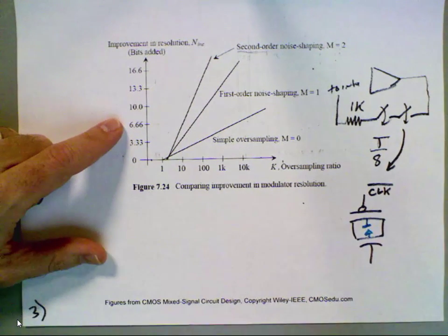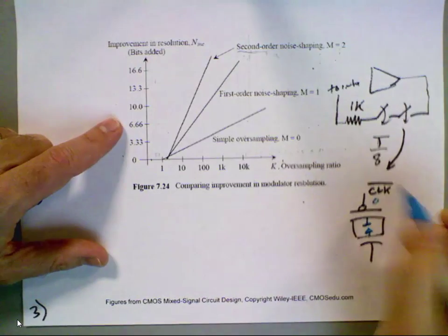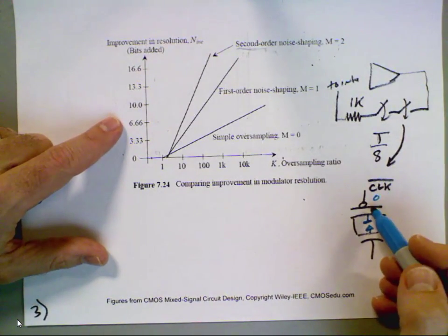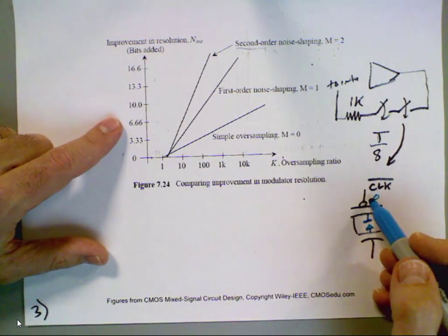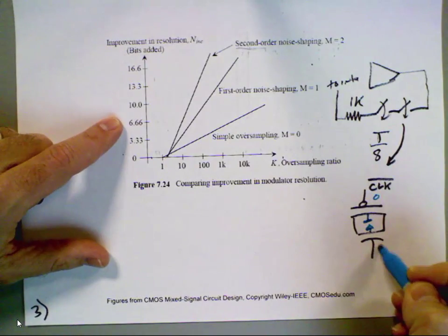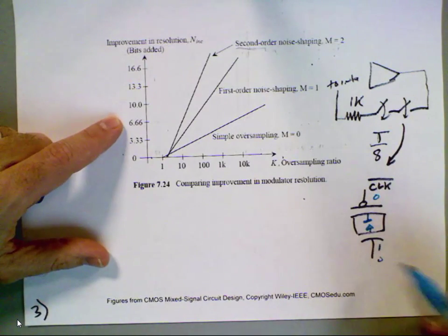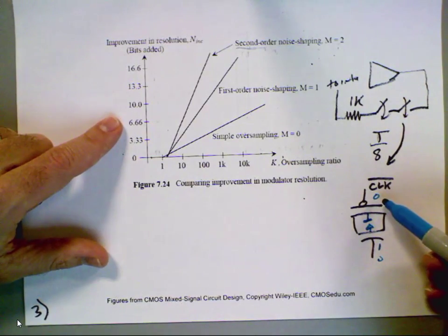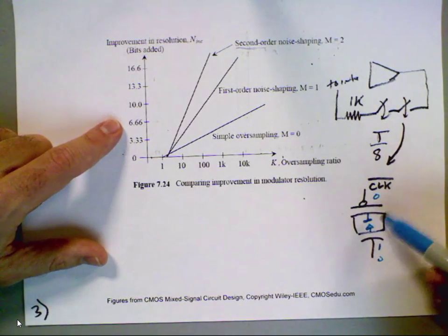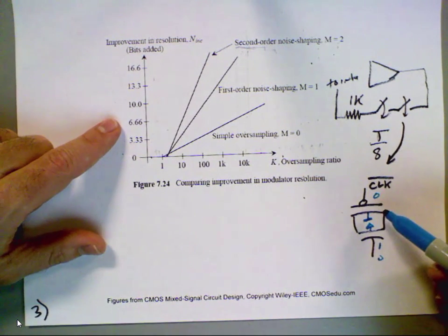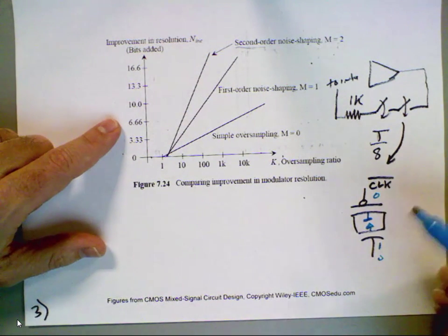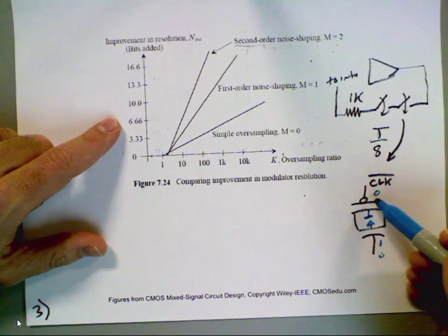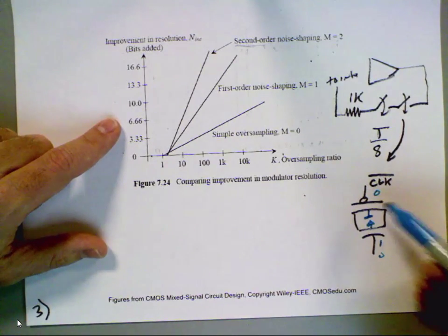The simple way to think of this is that when you put a 0 here, it turns the PMOS on. When there's a 1 there, it turns the PMOS off. Here, when you put a 1, it turns the NMOS on, and when you put a 0, it turns the NMOS off. That's why when we had our clock signals and we did our clock generator, it would be probably useful if you take out not only the true signal, but the complement signal so that you have one immediately available for clocking the TG. Does everybody follow that?